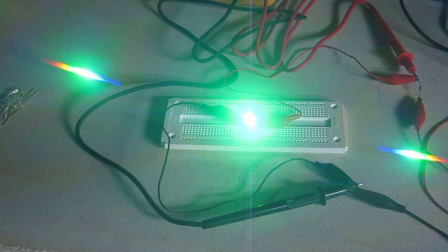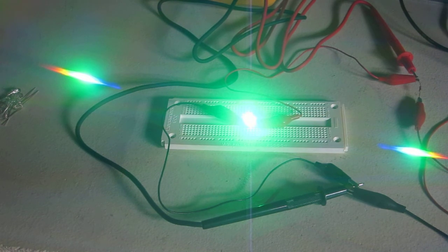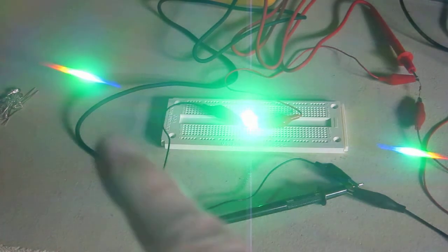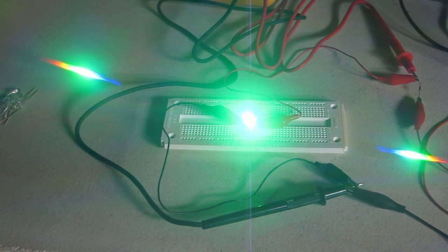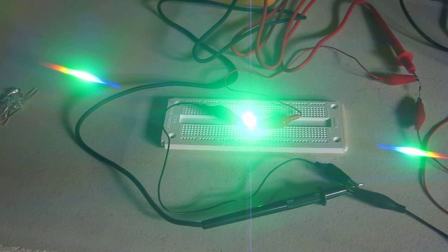So an LED is not exactly a monochromatic device. While it may look green to you and me, and there's certainly more output in the green than in any other region of the spectrum, there's also output extending off in either direction. In the case of red emissions, this side of the spectrum, we don't expect that, since that would infer automatically that there are transitions occurring within the band gap. However, the reality is there's impurities inside that gap, and so you're going to get longer wave photons than expected.